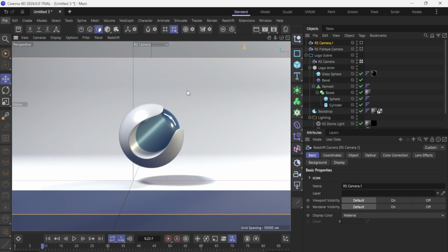easy to control. First, for a dynamic simulation, think in terms of two objects, a rotation object, which will move, and a base object, which stays put. Position them where they should pivot, and make sure the axis of the rotating object is exactly where you want the hinge to be. If needed, use the axis tool to line this up before connecting anything. Good axis alignment now will save you a lot of troubleshooting later.